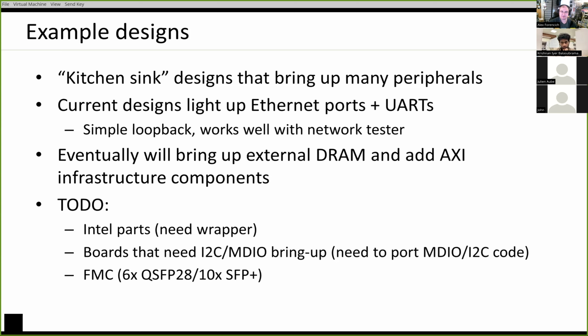Bunch of to-do items here. I need to support Intel parts and boards that need I2C or MDIO bring up. Those big high-tech level boards, you need to configure the clocking infrastructure on those via I2C. The VC1AT needs some MDIO stuff in order to work properly. So that sort of stuff is going to be a to-do once I get the MDIO and I2C code ported over.